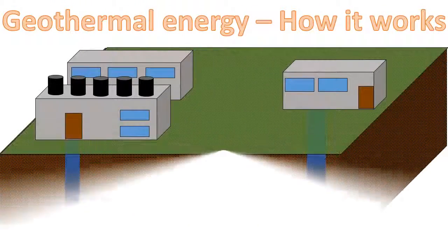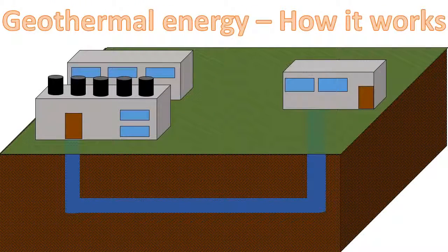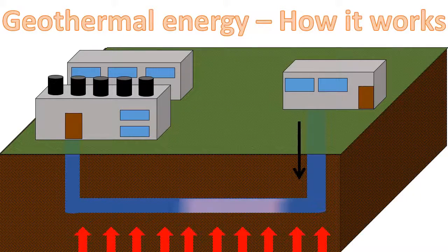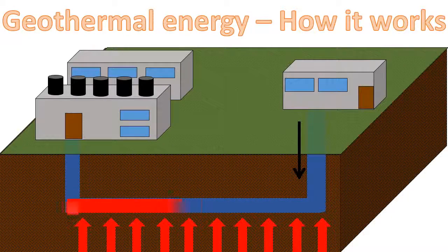In an industrial sense, geothermal energy can be used to heat up water or extract heat for electricity generation and heating/cooling applications. The former is achieved by injecting water through channels below the surface of the Earth. Here, heat will be transferred from the surroundings to the water, rising its temperature and converting it to steam, allowing us to produce usable energy. The latter is done by utilizing a heat pump to obtain or release heat to the ground.